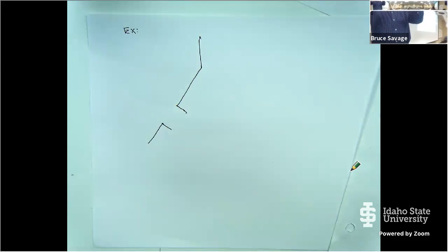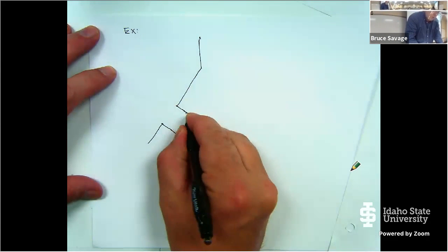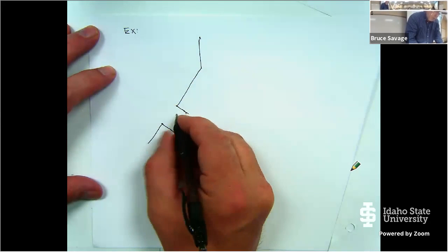I can now rotate that plate, and when it is parallel, the flow is going to flow past it. When it's perpendicular to the flow, it's going to shut it off completely. And when it's partially open, the flow is going to go around the cracks and go out. So I can control the flow with what's called a butterfly valve. It's a very common valve that we use usually for flow off and on, but sometimes it is used for flow control.